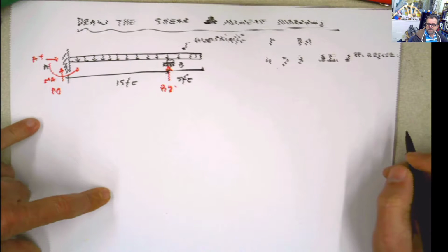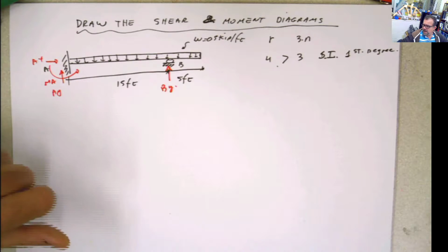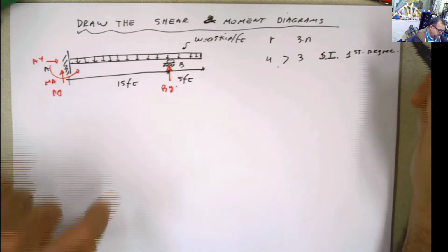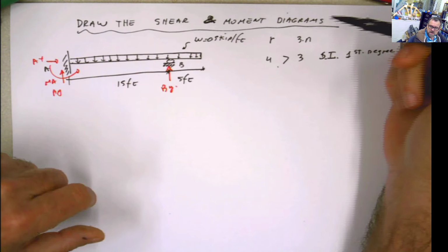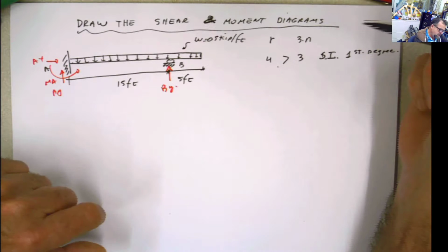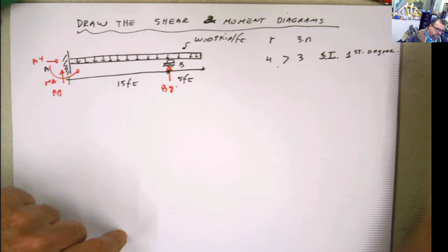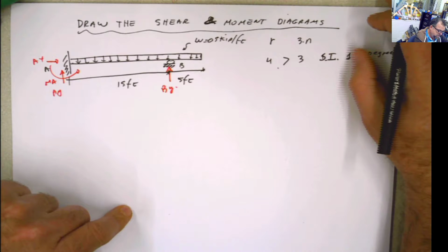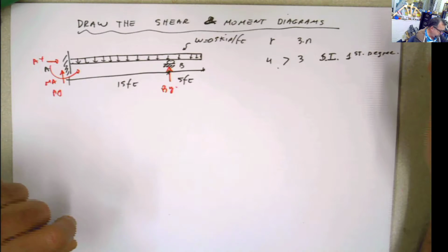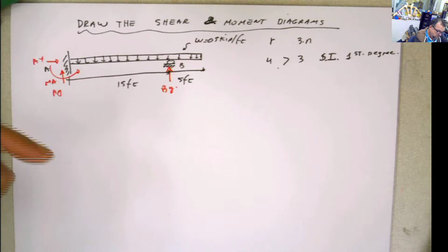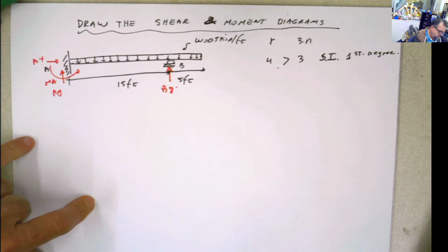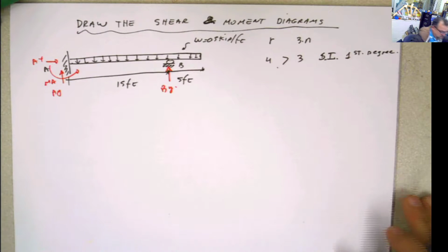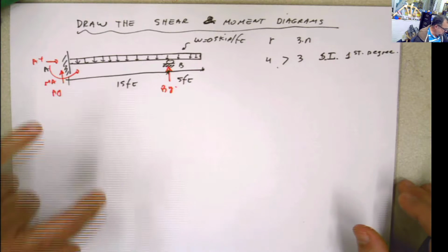Now it's different, because I want to draw the shear moment diagram, but first I have to find the external reactions. In order to do that, this is where what we were covering before applies: the method of compatible deflections, or the method of forces, also called consistent deformations, or flexibility. The first step is selecting one redundant. As I said, we're going to select one redundant.